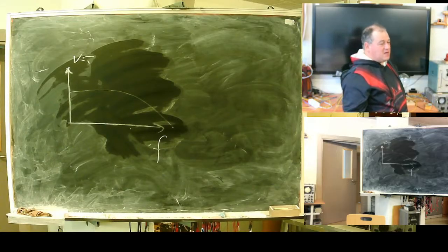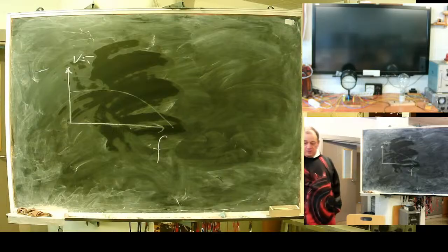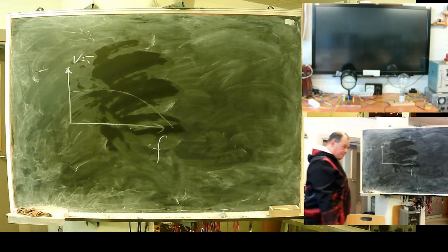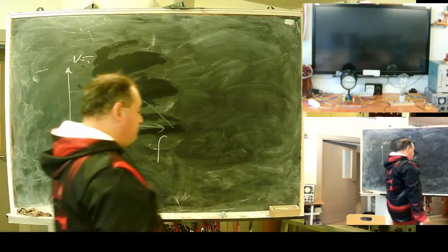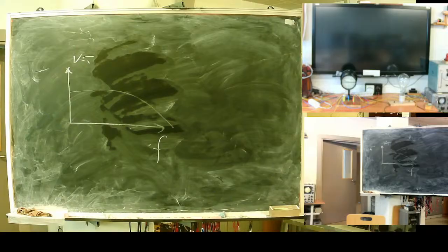Somewhere up to 300 Hz, then losses are growing, and you'll see a decrease of 30 to 50% in the signal. Ordinary transformer steels are not suitable for cases when you need to analyze high frequencies.